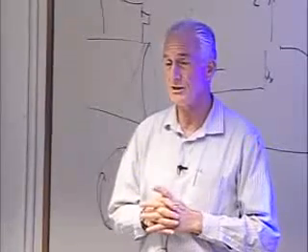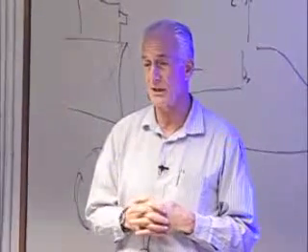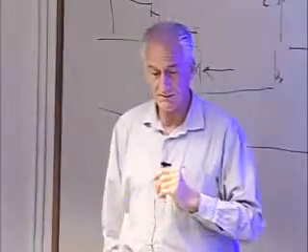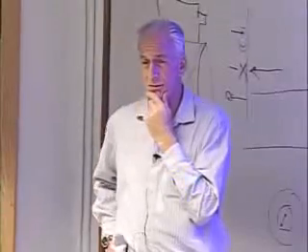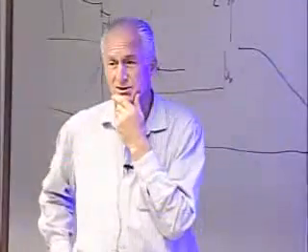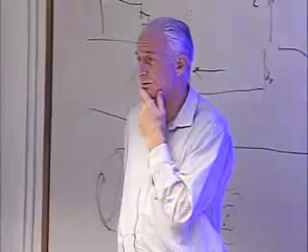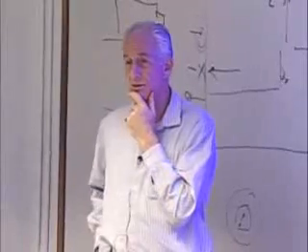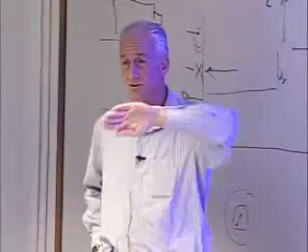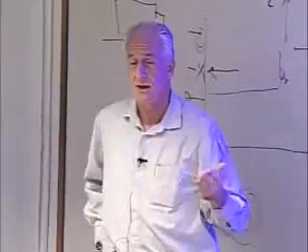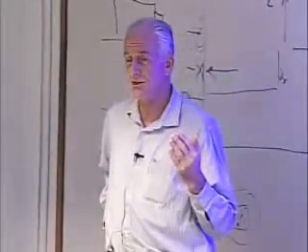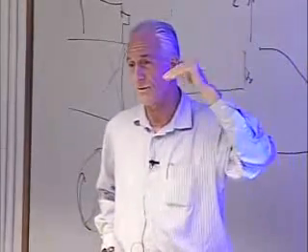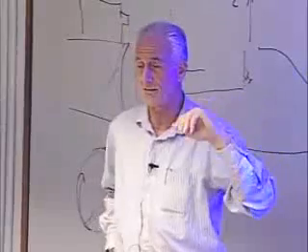And then finally it switches into the final approach and landing mode when you go around the heading alignment circle. That's the final step, which I don't think we talked about. Remember, I pointed out to you that since the shuttle is a glider, energy management is absolutely critical. And so you always come in with a little bit more energy than you're going to need, because it's easier to bleed the energy off through a series of S turns. And then they make the transition when you're essentially Mach 2 or Mach 3, and you're over the landing field, either in Florida or in California.